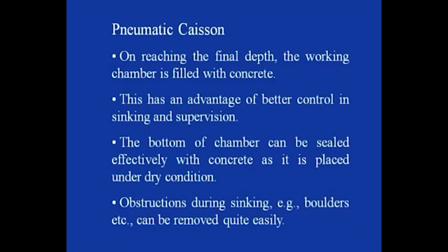On reaching the final depth, the working chamber of this pneumatic caisson is filled with concrete. Now this has the advantage of better control of sinking as well as supervision, because manually one can go inside and do the supervision. The bottom of the chamber can be sealed effectively with concrete as it is placed under dry condition.